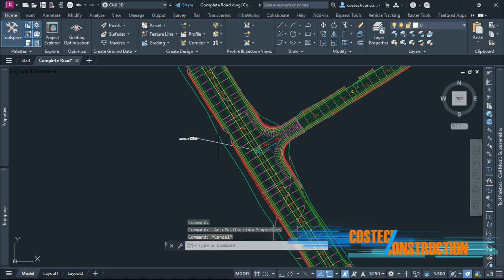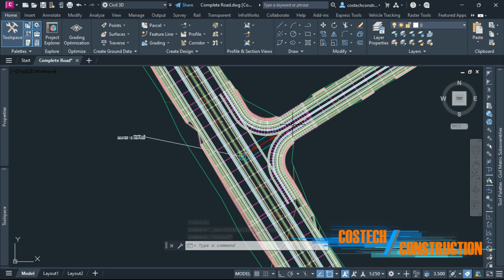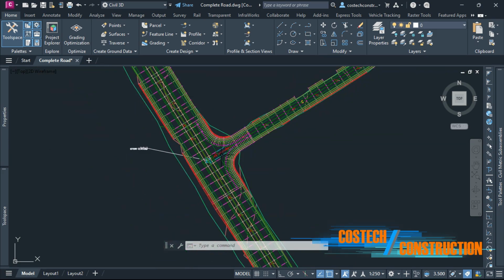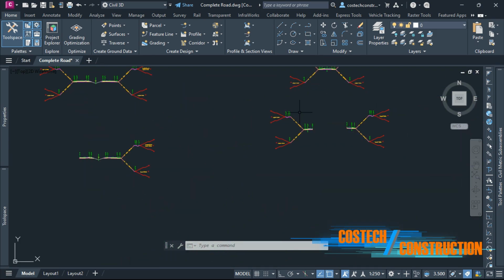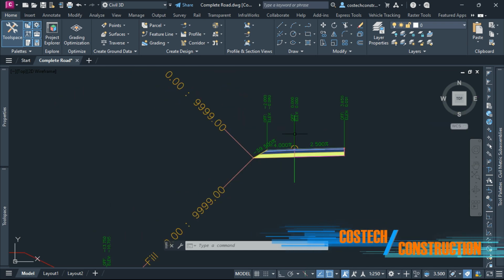We can now discuss how to set targets for our intersection by manually defining our width and elevation targets using offset and curb return alignments. This is the left curb return we defined in the previous video. Road 2 alignment is located at this lane edge in this assembly.